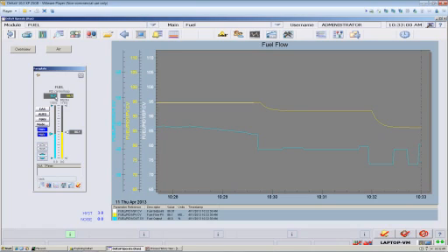If this was my only bump, if I didn't do all these things I've been doing for the last 3 minutes back here, my incorrect conclusion is that the gain of this loop is 1/4. I made a 4% change in output, and I see a 1% change in flow. Well, that's not the true gain of this process. What really happened is I have a loop that has a gain of 1 and a sloppiness of 3.